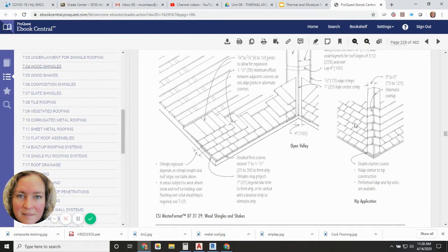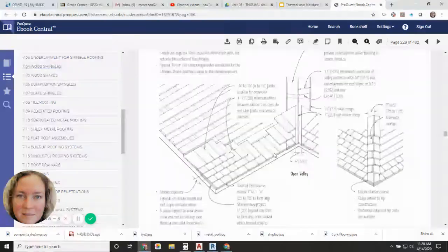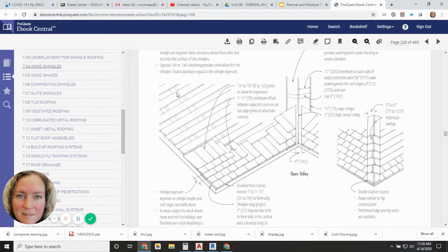The other variation you can get that looks like this are composite shingles, and usually those can come in clusters because they're stamped out of a composite wood and plastic. And then what they're showing here underneath is, instead of sheathing, furring on top of the rafters to hang all of the shingles.